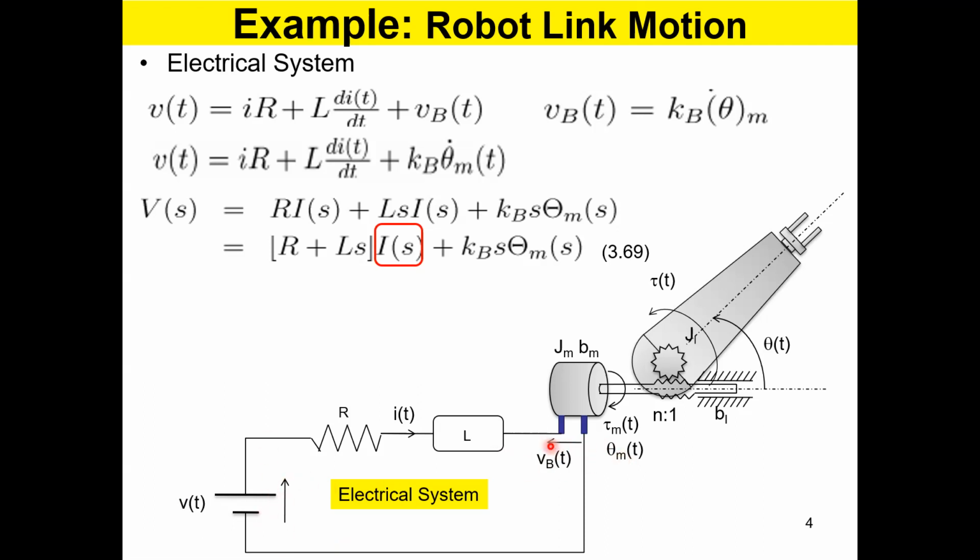So as the motor speeds up, this opposing voltage also rises up, right? So when you try to increase the speed of the motor, it doesn't give you the same quick speed increase, because as the motor speeds up, it will build higher and higher opposing voltage.